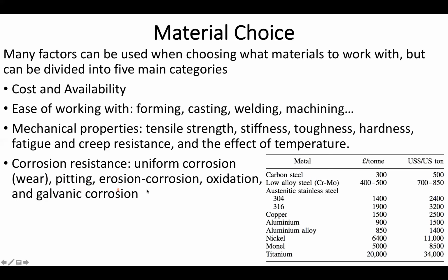And then you've got something called erosion corrosion. So erosion corrosion is essentially a combined process of I may have some sort of pitting, and then I'm going to see some erosion around that pitting site. So the erosion corrosion process can be a little bit more finicky. Then we have classic oxidation, and so oxidation can take place from many different sources, including, say, just oxygen.